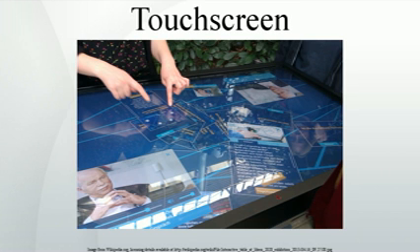Infrared grid. An infrared touchscreen uses an array of XY infrared LED and photodetector pairs around the edges of the screen to detect a disruption in the pattern of LED beams. These LED beams cross each other in vertical and horizontal patterns. This helps the sensors pick up the exact location of the touch. A major benefit of such a system is that it can detect essentially any inputs, including a finger, gloved finger, stylus or pen. It is generally used in outdoor applications and point-of-sale systems which cannot rely on a conductor, such as a bare finger, to activate the touch screen.